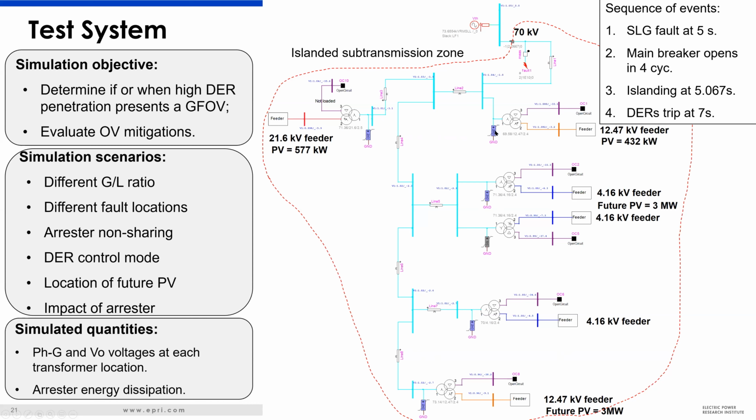So still one arrester could take most of the duty. And for arrester sensing, simulation suggested this option is also possible, by analyzing the current of the arresters. The pros and cons of this method depend on system configuration and need to be consulted with the utility. This is a look at the results. We are showing that the transformer 59 protection is the fastest to operate in simulated scenarios.